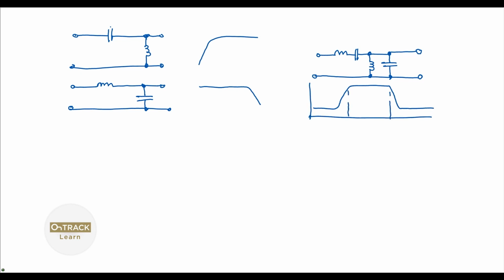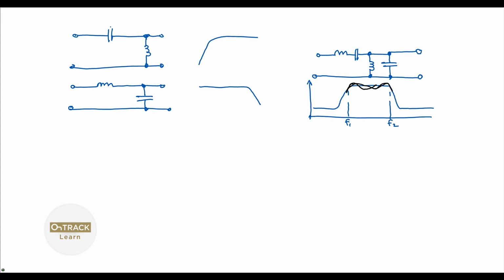And the bandpass, so you'd have F1, F2, and you would also choose those, not just to maintain system impedance and get the response you want, but to damp the filter according to the amount of passband ripple you want, because you know there might be something like this going on. Passband ripple. And there are many different types of filters that have different numerical techniques for calculating the component values, like Chebyshev, Bessel, Butterworth, elliptical, and so on, to get the kind of pass band or low pass or high pass response and slope that you need.